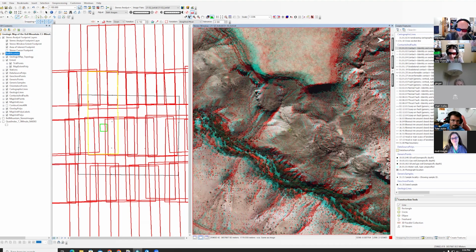And the reason why that's a problem is if snapping is turned on, it's going to create problems for you while you're trying to create features. And it'll also depend on what your snapping tolerance is, et cetera. I would like to work with all of you separately on that discussion point when we're in the tutorial, because the tolerances will be specific to what scale of map you're working on, et cetera.